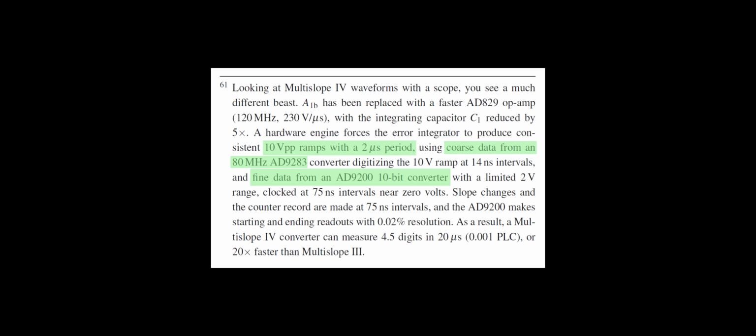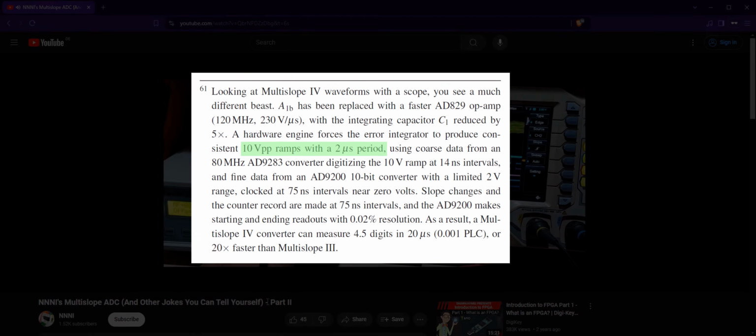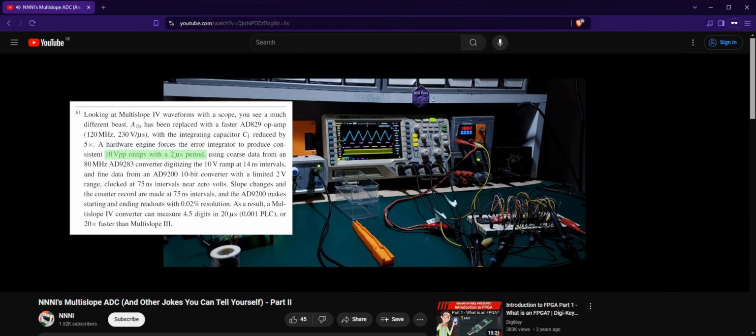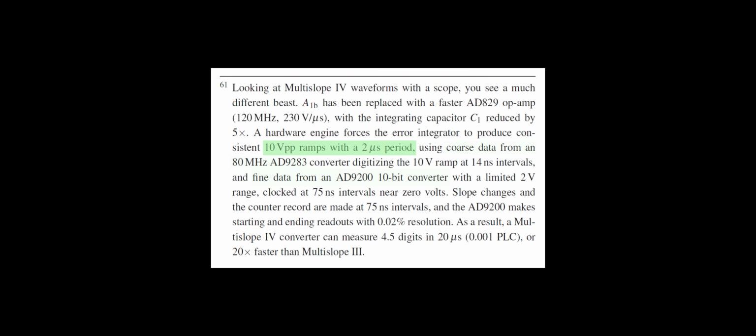conventional multislope wisdom. If the modulation frequency is constant, the average integrator level depends on the input voltage, and if the integrator swing is constrained, the waveform's frequency changes. Secondly, in addition to a fine residue reading ADC, a coarse ADC digitizes the integrator waveform for an unspecified reason.